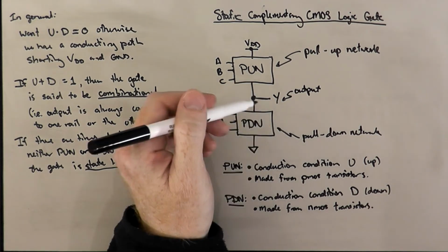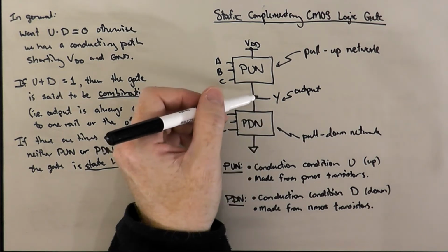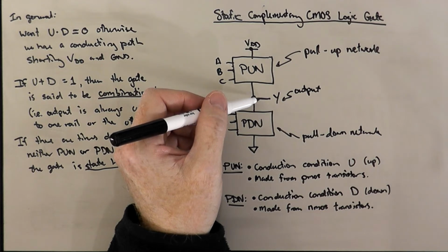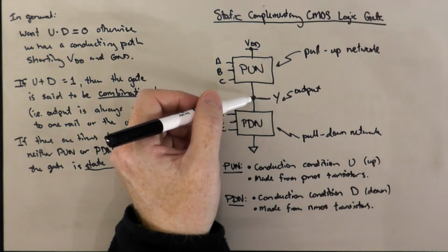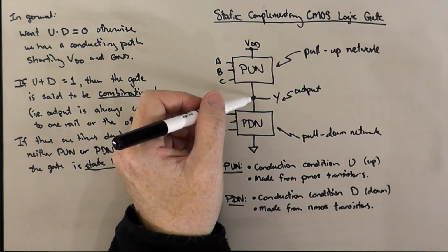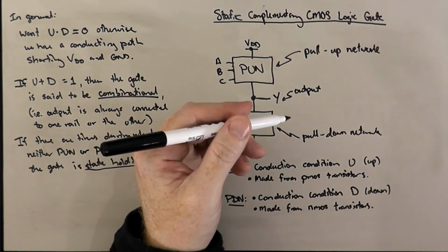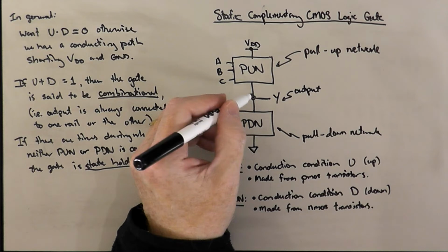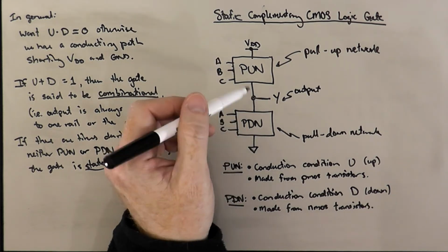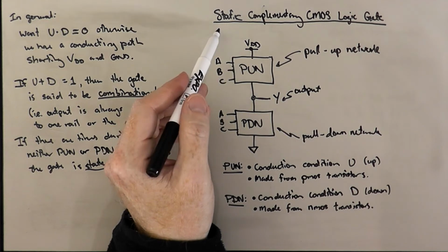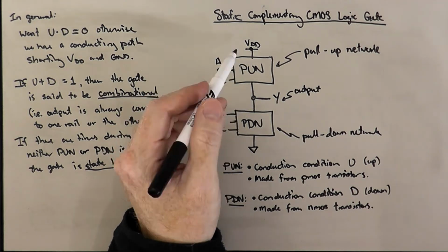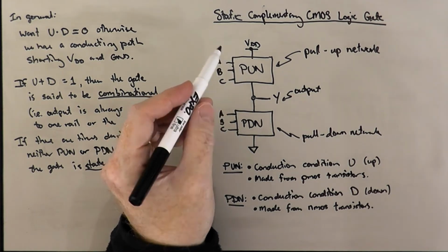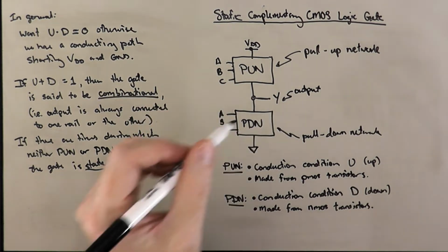And that could be just that there's some capacitance on this node like we've talked about before, and it's been set at some voltage and there's some charge on that capacitance. During that state holding phase, that charge will sit there on the capacitance, and as long as we don't disturb it somehow, that voltage will be maintained there. But that becomes what's called a dynamic node, and it's liable to be something that doesn't stay put. Leakage currents, capacitive coupling from other nearby wires and lines and things like that can disturb the node and corrupt the actual value of the gate.